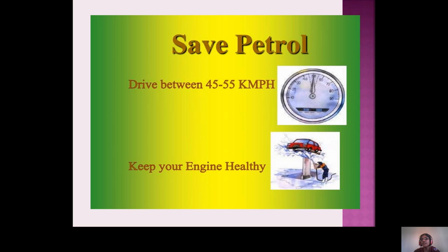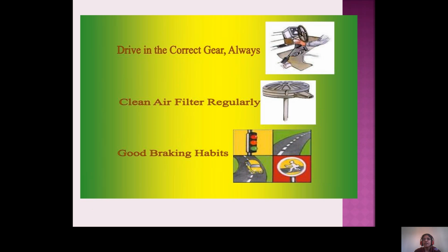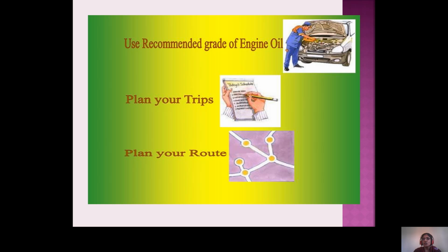Then keep your engine healthy. Drive in the correct gear always. Clean the air filter regularly. Follow good braking habits. Use the recommended grade of engine oil.